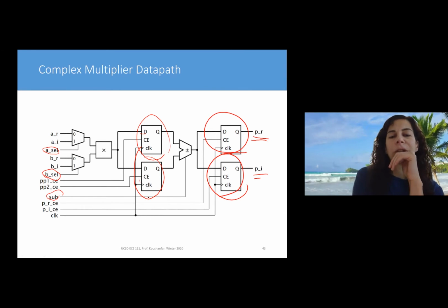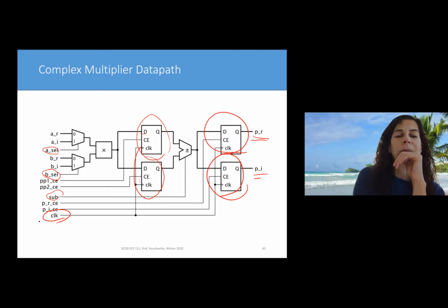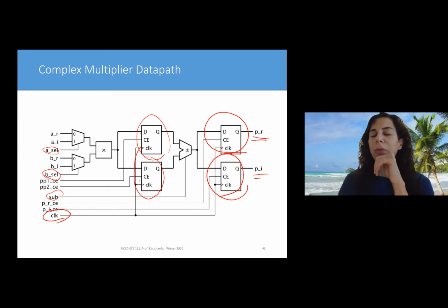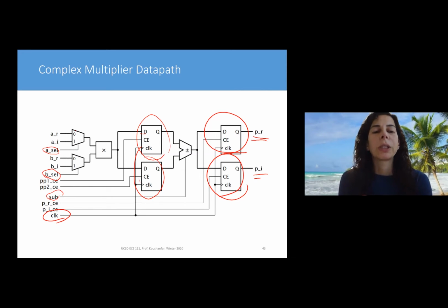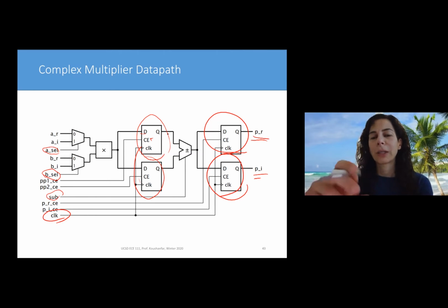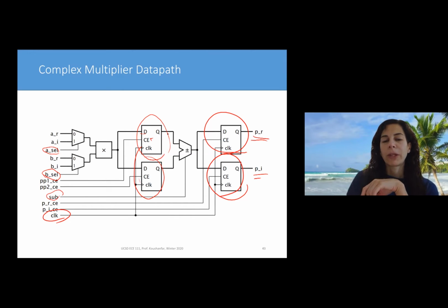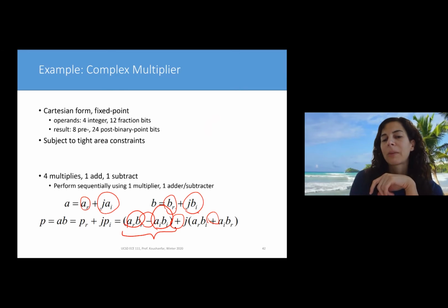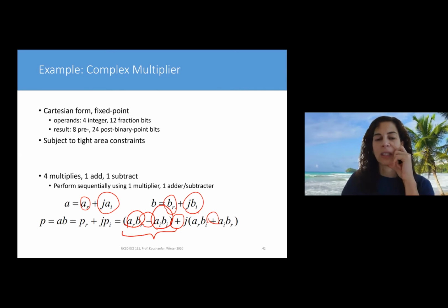Of course, these registers are all orchestrated by the clock, and as you can see here, the selector signals are pretty straightforward. I'm either doing the operation that is suggested, doing this multiplication and storing the result here, or I'm doing this operation with the signal selected here and storing the results here. And if I have these two results, I could go ahead and do the next operation because I have computed this one, and then I'm going to do this whole parentheses. And then I'm going to do the same with the second parentheses, and then I'm done.